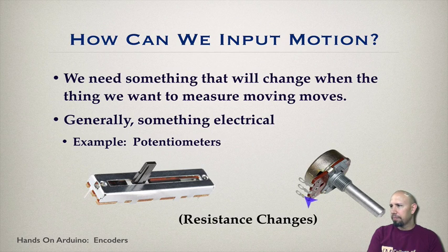It turns out that to use an analog signal basically requires an analog input. So often we may be limited by our number of analog inputs. The other issue is that for many potentiometers, you get maybe one full turn. You only get one rotation, and then there are stops on one side and on the other side. So you can only go so far using these kinds of potentiometers. Now, there are potentiometers called 10-turn pots, which will allow you to go more than one revolution. Okay, so it's possible that you can use one of those.